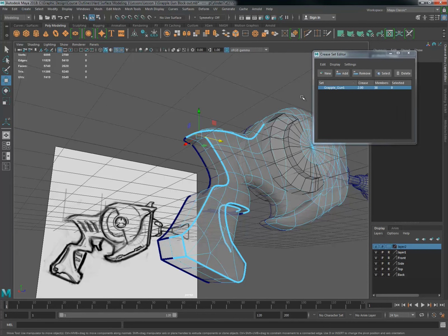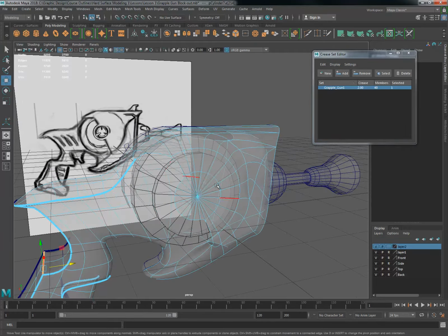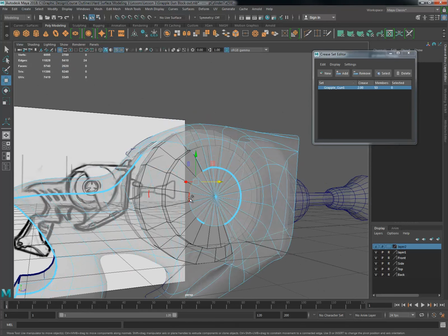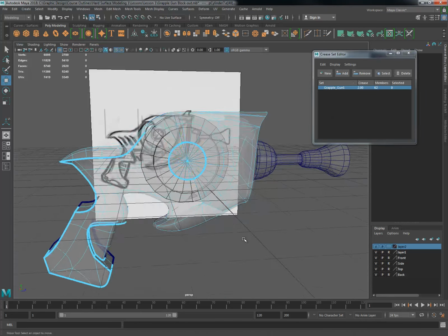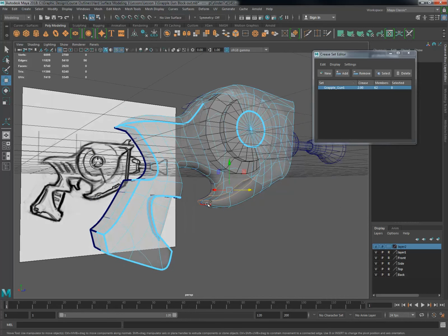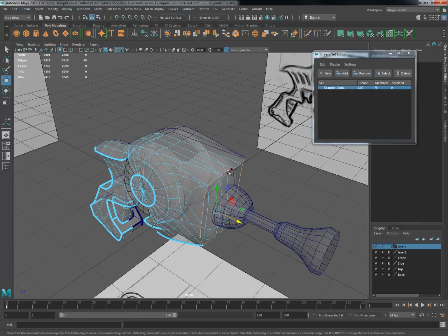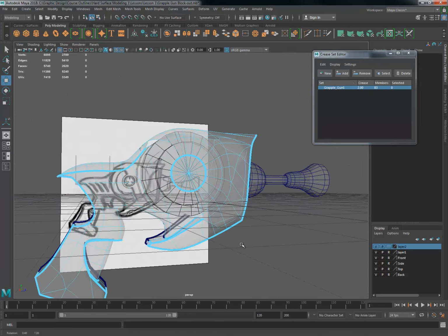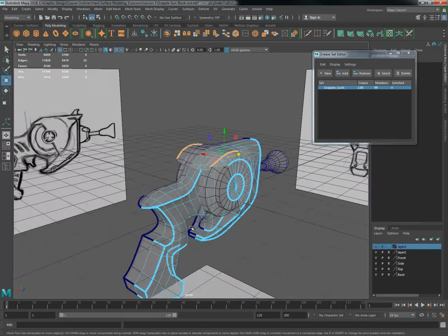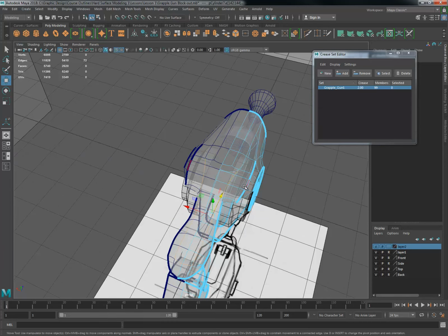And you can also delete creases easier this way. They tend to get stuck on the model, and there's no way to get rid of them when you just crease without doing it through the Crease Set editor. And if they do get stuck, and you can't remove creases you don't want creased through the Crease Set editor, all you have to do is make another crease set, add them to that crease set, and then press remove, and you will be able to remove them.